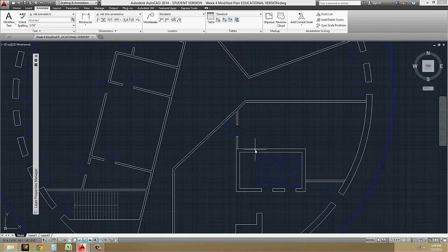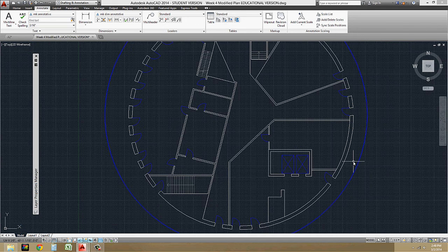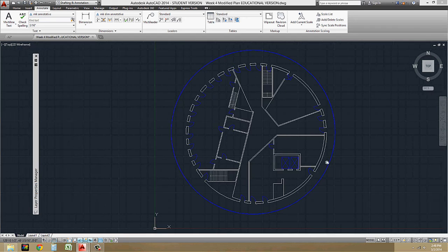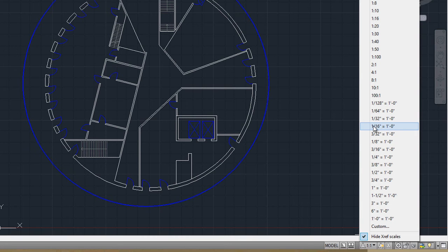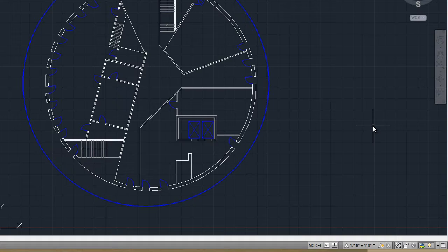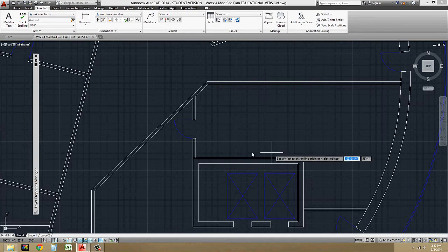So that is setting up all of my notes and my dimensions to be at full scale. Theoretically, what I just put in there was as if my notes and my dimensions were literally at full scale, as if that text was literally 1/8 of an inch high. And obviously that's not going to show up on our 16th inch drawings the way that it was showing up there. So we need to set up our annotation scale to recognize the 16th inch, and as I said, it's going to do the scaling for us. So I'm going to expand this list. I'm going to click on 1/16 equals 1 foot 0 inches, and now I'm going to add my dimension again.